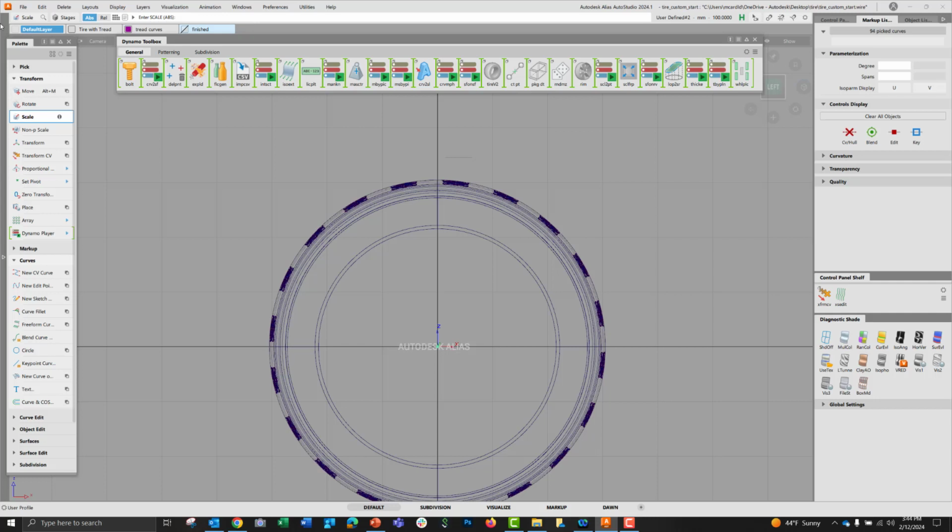Next, I'm going to use the Rectangular Surface from Curves tool, which is the second tool in the General tab. And this will create a plane around all the outermost edges of these text curves. We'll need to use this as an input for another tool. The prompt line is asking me to pick the curves to cover. So I'll select all these letters and press the space bar, and I've got this plane created. I'll copy and paste, move it up a bit.